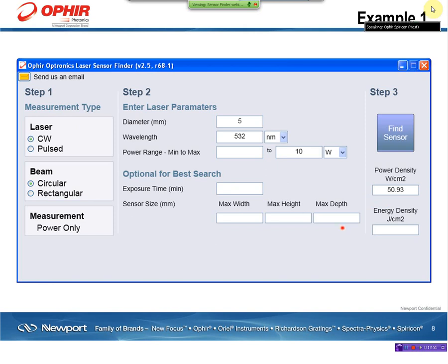I should mention, by the way, that the power density is calculated very simply. Pi r squared is the area of the beam. So if I take 10 watts and divide it by pi times 0.25 centimeters squared, I get my power density. Now, you're probably thinking to yourselves, yeah, but that's only assuming that the distribution of the power through the beam is uniform. You're absolutely right. There are all kinds of safety margins that need to be built in, that are built in. This power density calculation, you're absolutely right, is assuming a uniform or top hat distribution. If you know that in your application it's very much not like that, you'll want to take that into account and take a little bit extra safety margin into consideration in the next step. So now let's look at the next step.